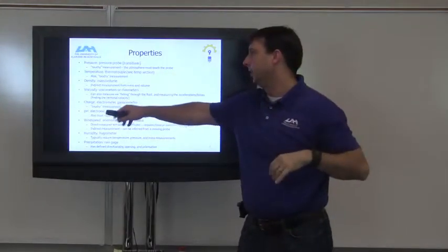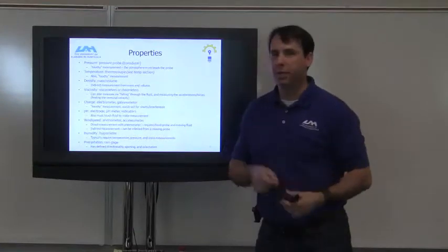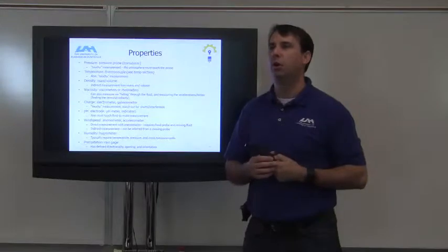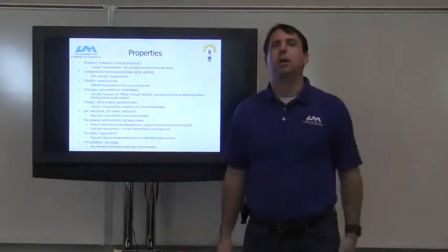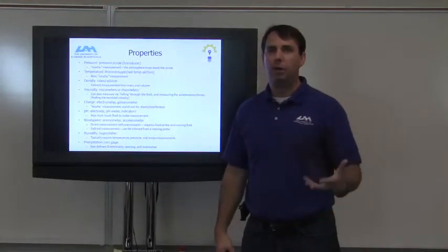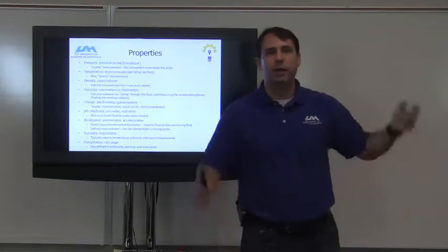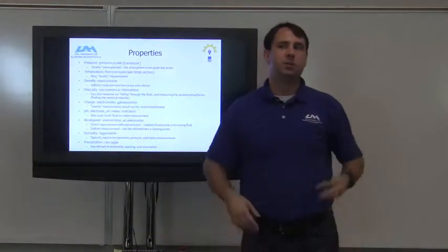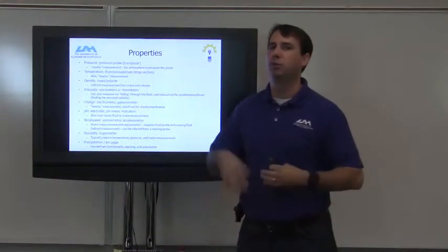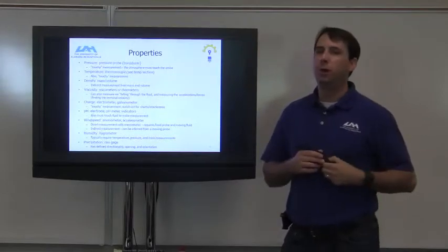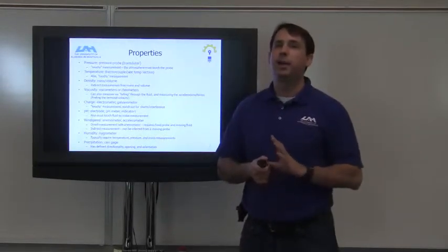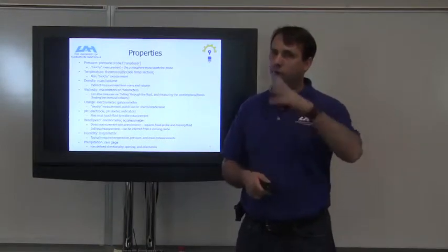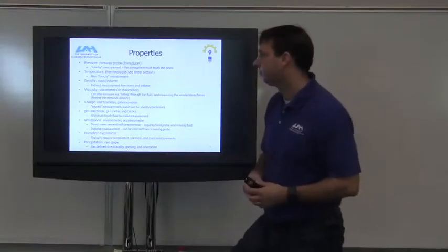Charge is measured with electrometers or a galvanometer. It's a touchy measurement. Also, you actually have to touch the charge that you're measuring. Charge is not just a number. Charge is based on a relationship, usually to ground, okay? And so you can't just measure a charge by itself in the middle of nowhere because there's no reference point. Charge requires a reference point, basically. So if you want to measure charge of an atmosphere or something like that, you have to have a reference point that you're measuring it against. And we can talk about this if this is what you want to do.